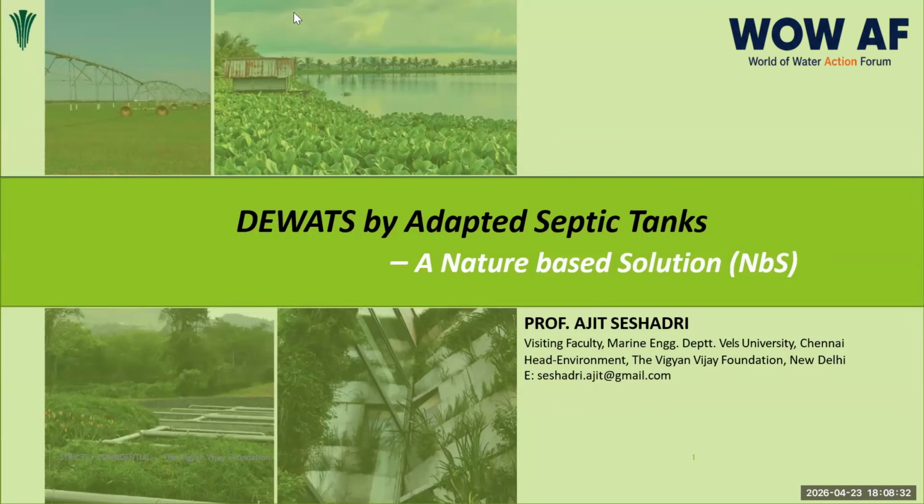The septic tank having all these things will be followed with a simple collection tank where we will get in the gray water, in case gray water is there in the campus. After it is equalized over there, we will take it to the phytoremediation plants, and I will be mainly concentrating on giving you the hydraulic retention time.